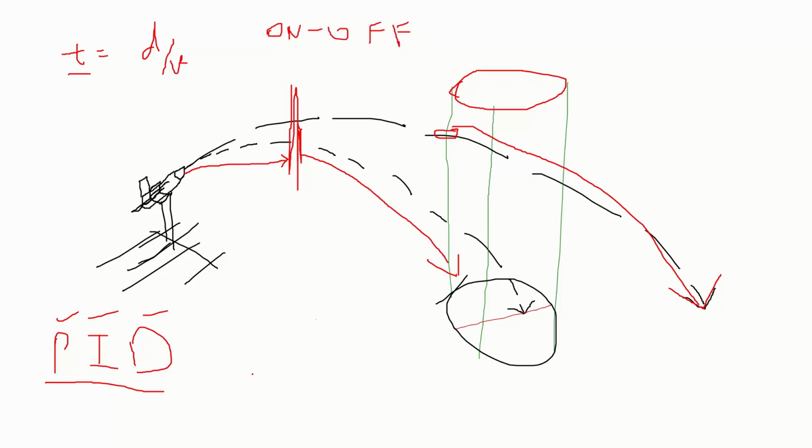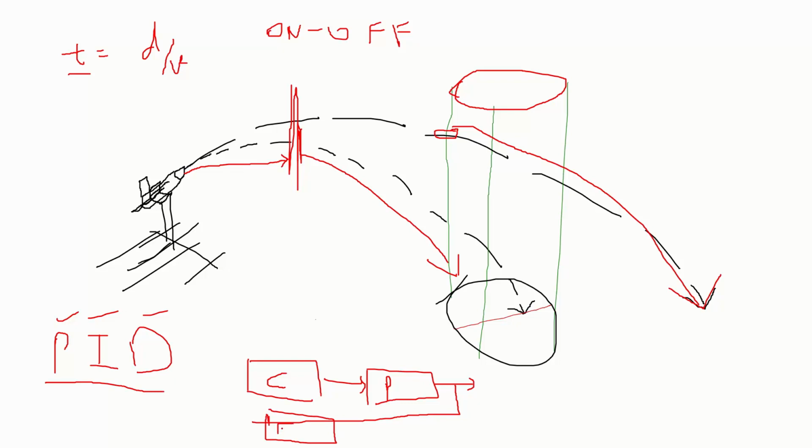So what it means is that you will be having a controller. Let's say we represent the controller by C. Then you have the plant or the process that we represent by P. Then you have the actual output. From this actual output, you give a feedback. For this, you might be using sensors like radar antennas. So let's say FB represents the feedback. Then this feedback is given to a comparator, an input here with a plus sign as with the reference input. So this generates the error. The output at the comparator side generates the error, and it is this error which operates the controller. So whenever you have a finite error, the controller will be operated. Otherwise, the controller will switch off if the error is zero.